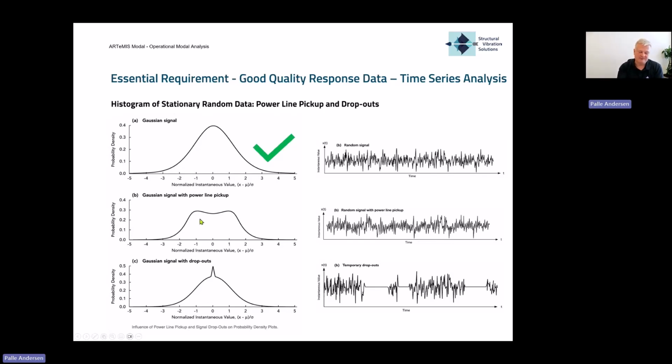And when you start finding the histogram of a channel that is mixed with sinusoidal excitation and random excitation, normally distributed, then you get this kind of form here where it's going to be a little flat, like you can see here, but it still has a little bit of the two spikes here. It can be more or less, but it's quite easy to see that it is not really a normal distribution. You have something on both sides there that indicates that you have a mix with some sinusoidal excitation.